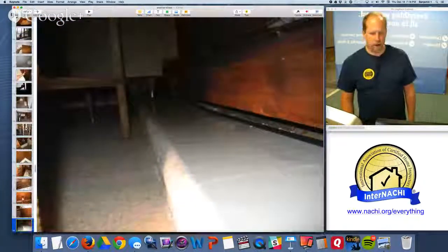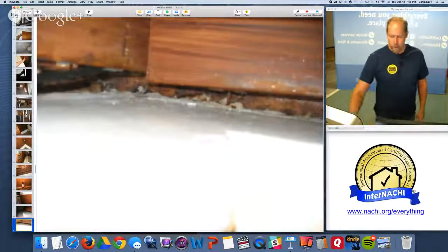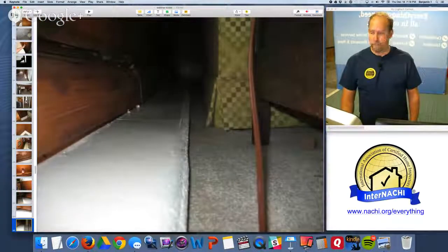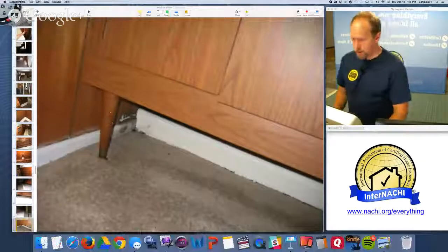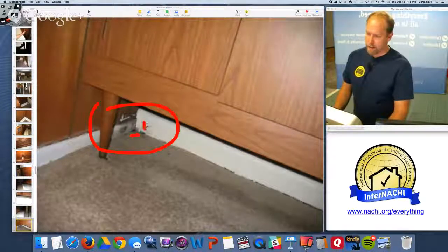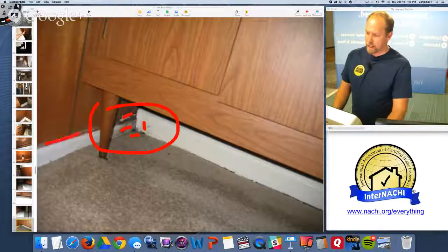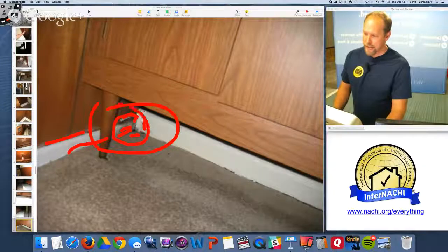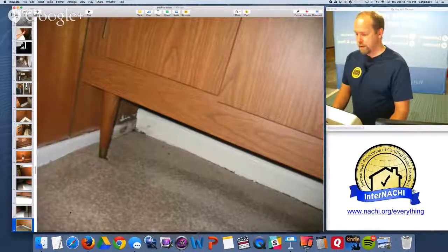Looking for any indications of water now. And there's rust. So that's the baseboard radiator system, and it's totally rusted. So water rusts metal. There's indications of water penetration here as well. On several surfaces, the carpet has a stain, the baseboard trim has a stain, this trim has a stain, this wall paneling has a stain. It extends all the way over here. This has been painted over to make it look good, but I think this is after it's been painted. So right now I'm just calling it out as active, right?